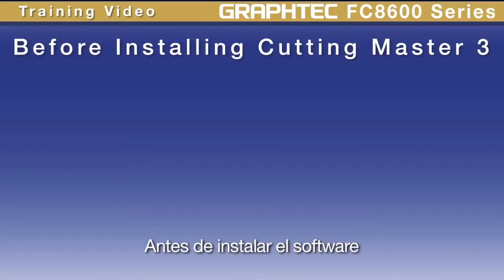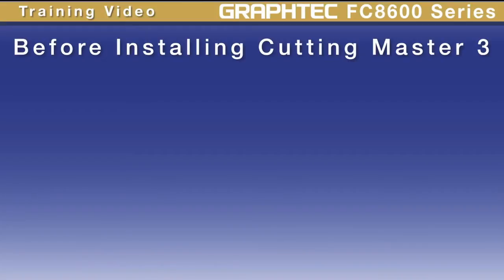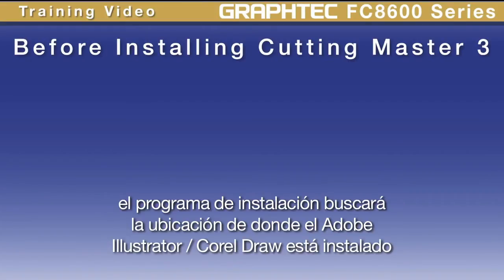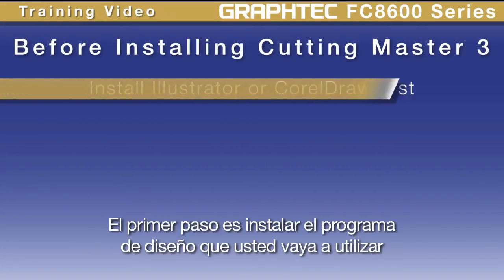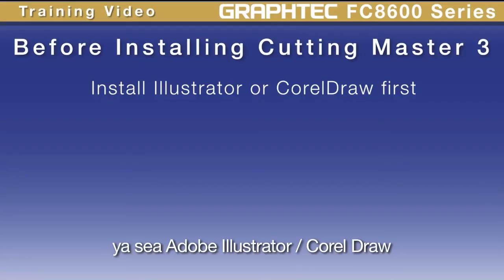Before installing the software, there are a couple of steps that must first be taken. When installing Cutting Master 3, the installation program first looks for the location of where Adobe Illustrator or CorelDRAW is installed. This means that these programs have to be installed prior to installing Cutting Master 3. The first step is to install the graphics application you plan to use, whether it is Adobe Illustrator or CorelDRAW.